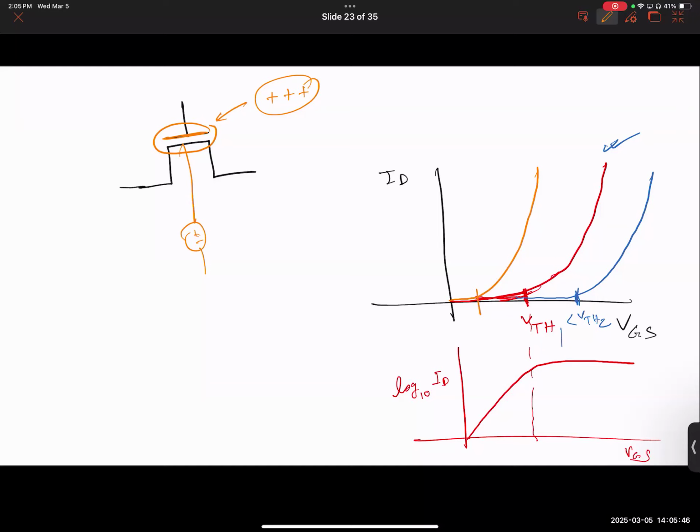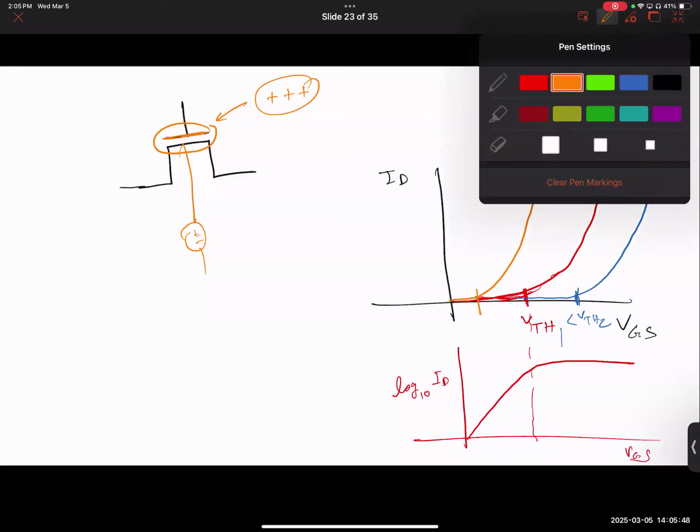All right. So keeping that in mind, let's talk about the ferroelectric transistor. You have ferroelectric added to the gate. This is a ferroelectric transistor, and the ferroelectric material could be set in positive polarization or negative polarization. So imagine when you have positive polarization, you have a certain threshold voltage.